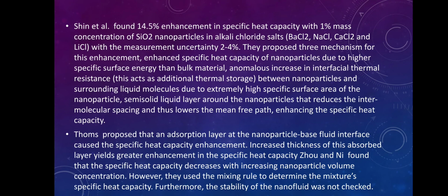Anomalous increase in interfacial thermal resistance between nanoparticles and surrounding liquid molecules due to the extremely high specific surface area of the nanoparticle. And a semi-solid liquid layer around the nanoparticles that reduces the intermolecular spacing and thus lowers the mean free path, enhancing the specific heat capacity.